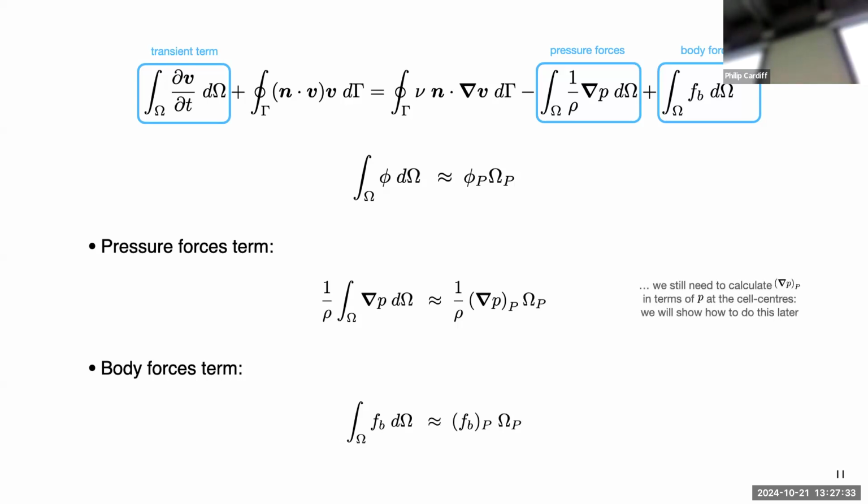And the goal of this discretization process is the unknowns, which for incompressible Navier-Stokes are the pressure at the cell centers and the velocities at the cell centers. So we write these equations in terms of the velocities and pressures at the cell centers around a particular cell within the molecule. By that definition, we haven't quite got there.